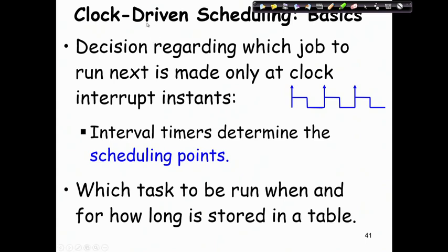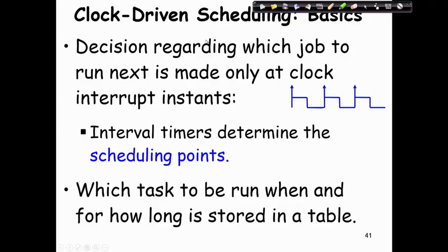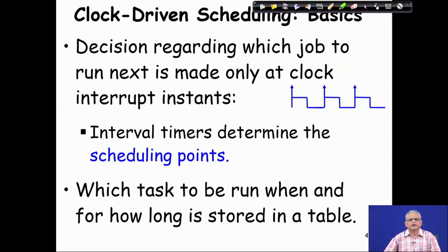So, all these schedulers that we are looking at are at the simplest end of the real time operating systems, and these are called the clock driven schedulers. The ones that are much more sophisticated are the event driven schedulers. So, we had in the last discussion seen that there are two broad categories of real time task schedulers.